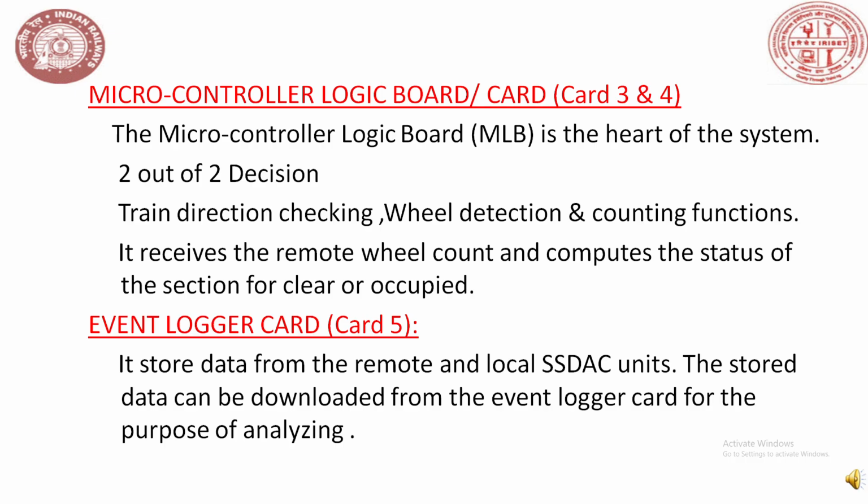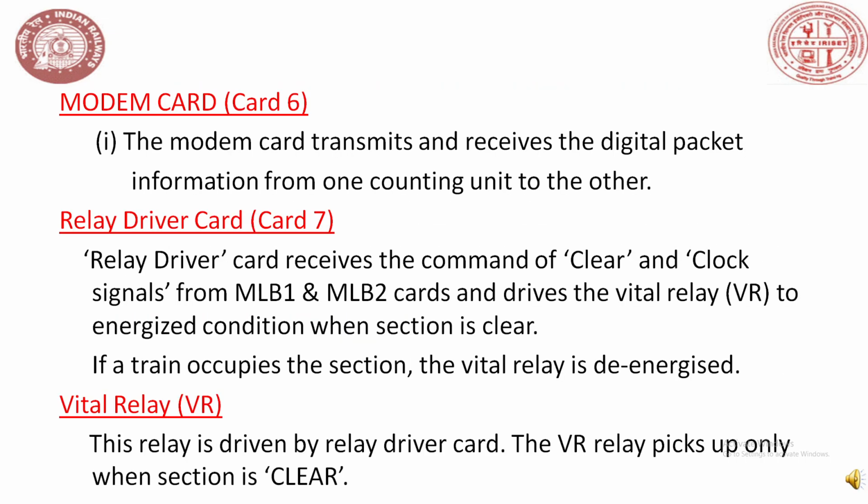Event logger card, that is card number 5. It stores data from the remote and local SSDSC units. The stored data can be downloaded from the event logger card for the purpose of analyzing. Modem card, that is card number 6. The modem card transmits and receives the digital packet information from one counting unit to the other.